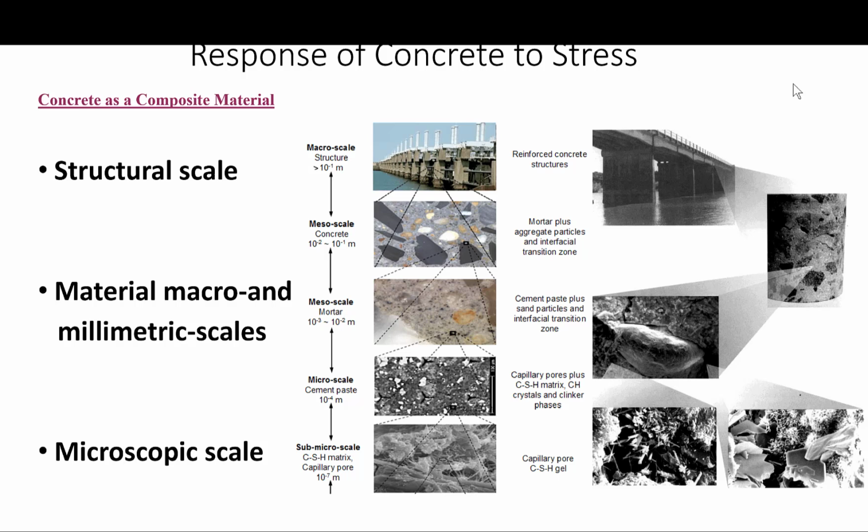Even under such conditions, however, the response of concrete is sensitive to the nature of the tests, including the degree of restraint, the moisture content, and the rate of loading, since there is virtually no aspect of the mechanical behavior of concrete that is not affected by these factors. So remember, the sensitivity to testing, the rate of loading, the testing regime we are using, all make a difference.